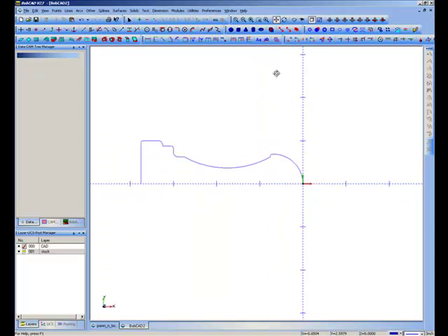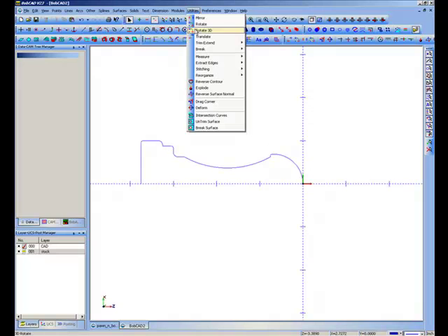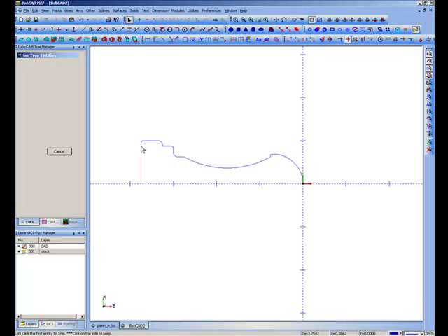There we are. And we have to enable lathe mode. So you click on that, and it's the same as going up here and clicking right there. You can see I'm already in turn mode. Let's create some stock, and basically it's just going to be a square the size of the pawn we want to do. So we don't need the fillet that we designed in to create the solid, so we can go to trim, two entities, and I can click on that one and click on that one and get my square corner there.